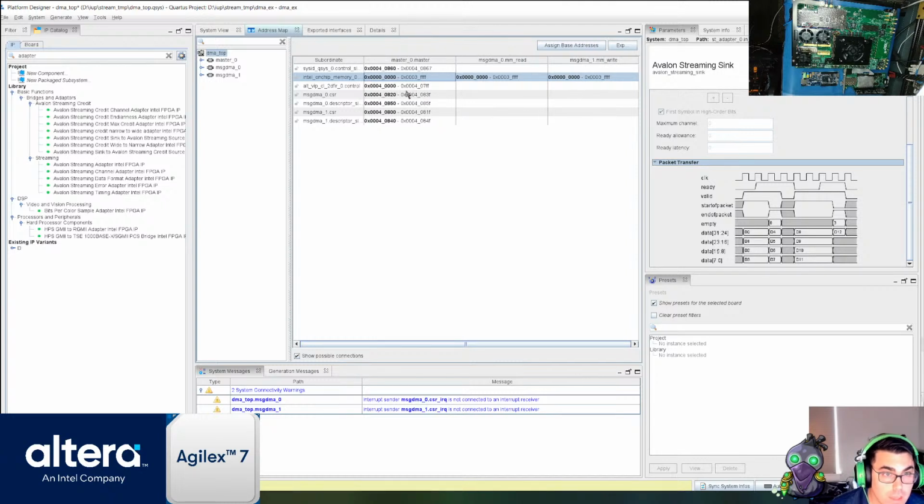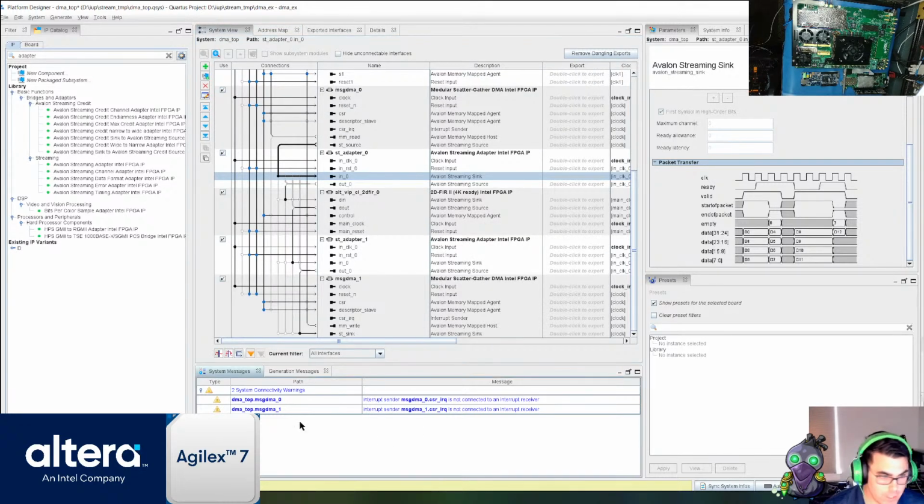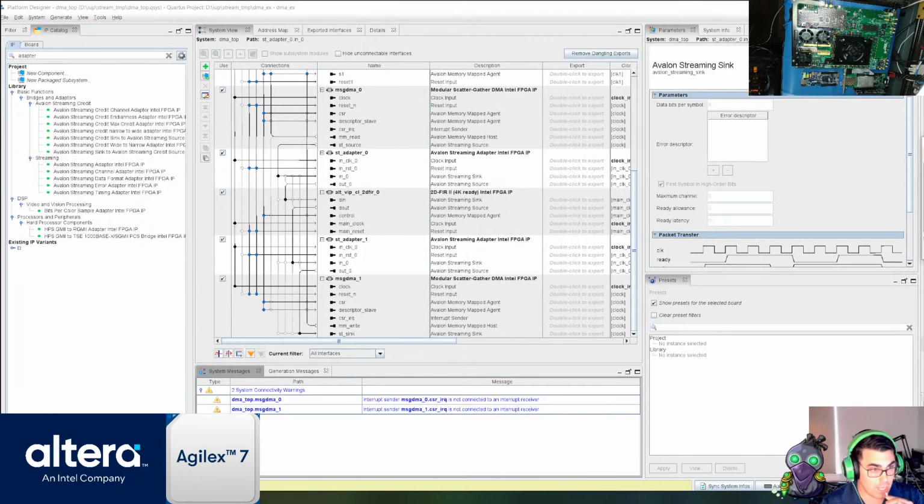This is at 4000, okay. 250, yep, and 40. Oh, this control one is 4600 and 40. Okay, that lines up. Cool. Everything's happy. We don't have any interrupts to use, so we don't need to connect those. Let's go ahead and save it, and we'll build it. Then I'm going to show you how to add a Signal Tap to the design.